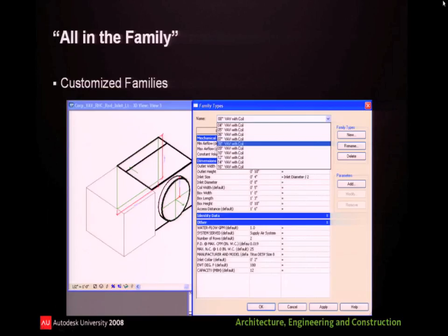Early on, when we had our strategy of just doing ductwork in Revit, and I talked about all the components we had to build families or use families out of the box, VAV boxes is one thing I looked at right away. We customized our VAV box so we could pick up the flow, bring the flow through, and how we did our customized box, we created types for each size of an inlet. Your typical Titus or Price, Tuttle Bailey, they're all pretty much the same. They have 4-inch inlet through 16-inch inlet here.